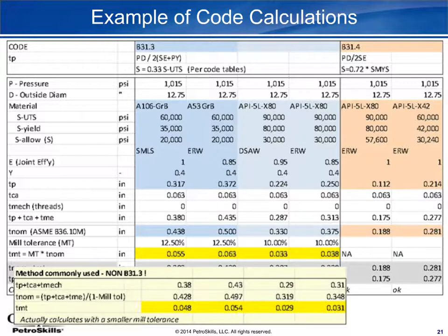Based on the challenges you may encounter in welding X80 material, and the fact that 0.188 is so thin, companies will often have minimum wall thicknesses from a general fabrication perspective, for mechanical strength issues. Often we say a 0.250 minimum wall thickness, in which case X42 does that quite nicely.